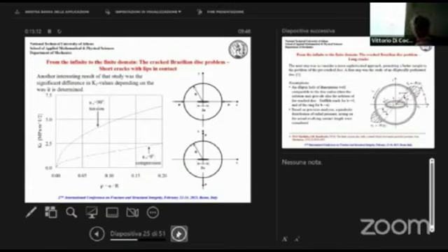When we calculate mode 1 stress intensity factor, we suppose that the crack is under opening mode. We have to apply tensile loads. What do we do in practice? We apply compressive loads parallel to the crack, and we assume that these two configurations are identical. They are not. In case we adopt the ISRM suggestion, the fact that the curved jaws impose restraints does not permit simulation and identity of these two configurations. The difference is huge. So what we are getting by using the ISRM standard is perhaps not the actual stress intensity factor under mode 1.